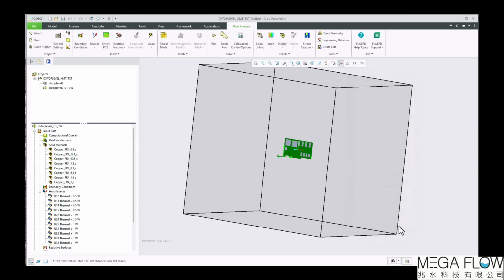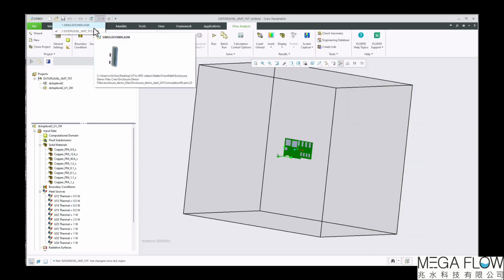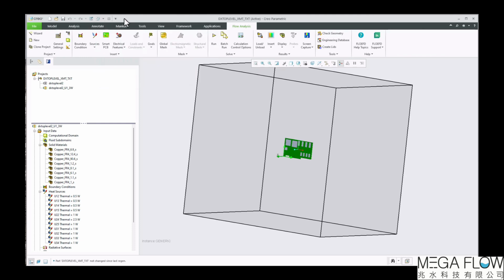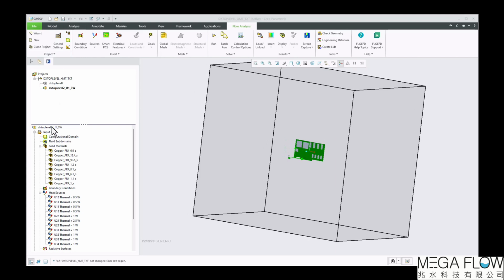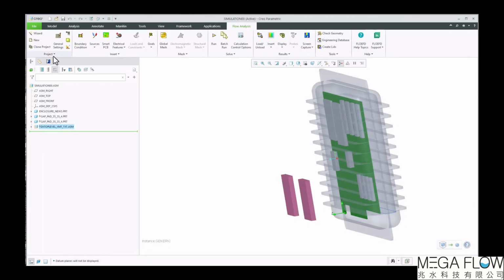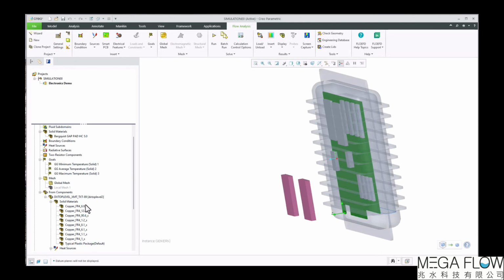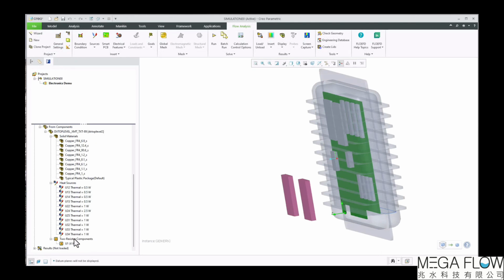Hit OK. Now at the top here, we can see we have our 2 projects, the main project and the sub-project. I'll go ahead and save this sub-project. Oh, and actually, let's also remember to rebuild the project, then save, and then we can close this sub-project. And now if we look at our subproject here, we see we don't have the goal here updated. So what we need to do is right-click on From Components and hit Update All.